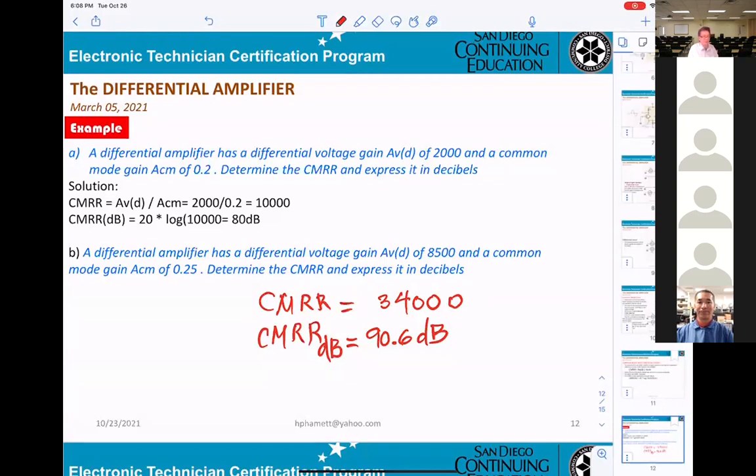However, the noise at the input can be 1 volt. So you cannot see that 1 microvolt or 1 millivolt signal with your scope. Your signal will be buried inside the noise.